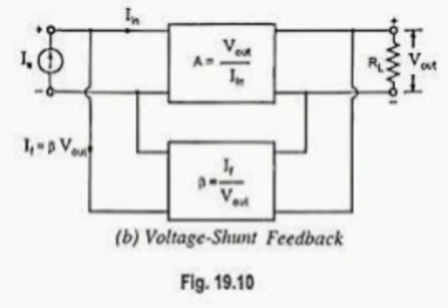Transconductance amplifier: input is given in series to beta and output is given in series to beta, that is called current series topology. Unit of beta is ohms. Current series feedback stabilizes the transconductance gain. Example: common emitter. Voltage shunt topology.